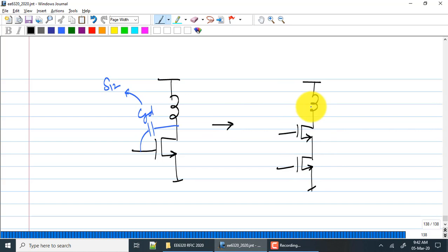Now maybe towards the end of the course, if we have time, we can have a separate set of lectures on how your design will depend if you're building millimeter wave circuits instead of regular RF circuits. But for now, let us leave it at this because we're going to come back to this during power amplifiers. So just hold your questions till then. Because in power amplifiers, these devices will be extremely large. Even at 2.4 gigahertz, CGD will be extremely large. All your capacitance will be extremely large. So S12 will be very small for power amplifiers.